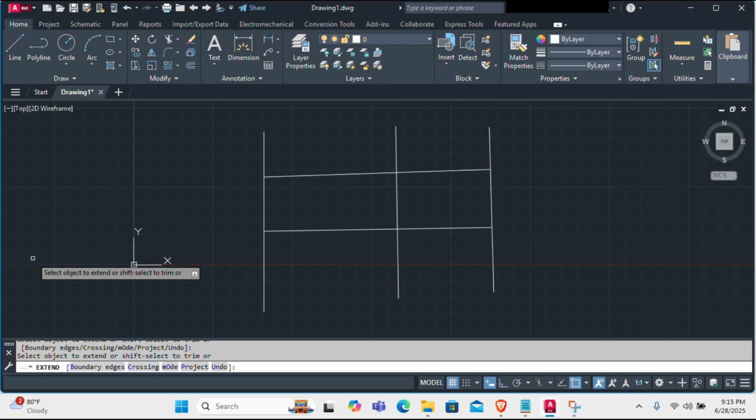So this is used when drawing the rungs or wire jumps that stop just short of your ladder rails. Extend snaps to the nearest possible edge. No need to worry about the coordinates. Now another cool thing is you don't need to switch tools all the time. Simply you can use shift to switch between extend and trim.